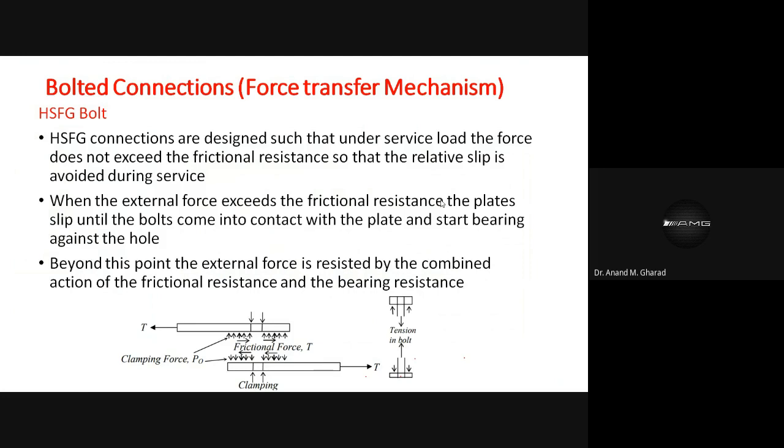Okay, and when this frictional force gets surpassed, the plate will then come in contact with the bolt, and once it is in contact, bearing stresses will develop. If these stresses are crossed, or if the bearing limit is crossed, then it will enter into the shearing failure zone. So it's a very gradual process. It takes time for the bolt to enter into the bearing stress phenomena.